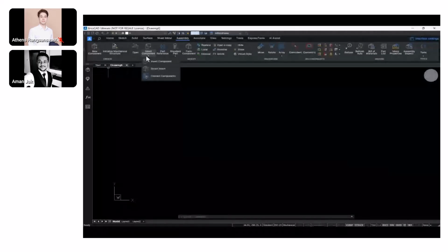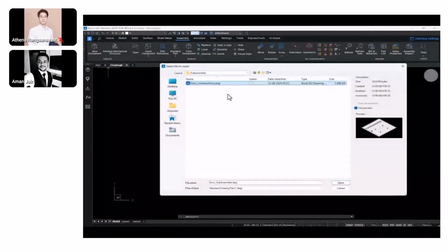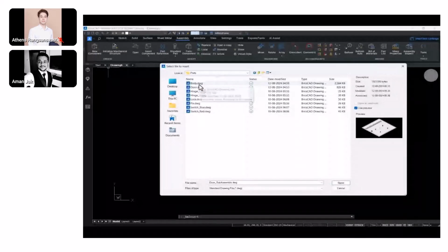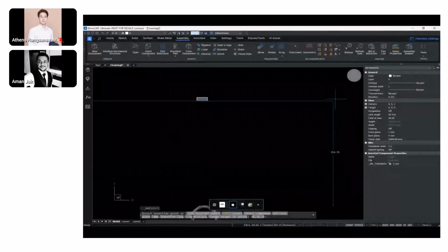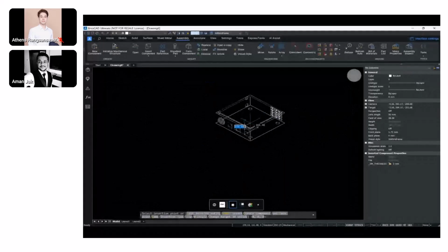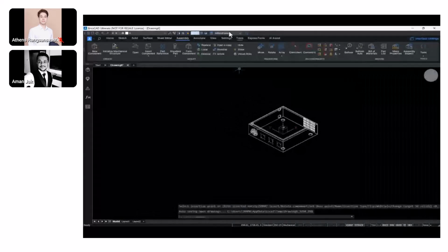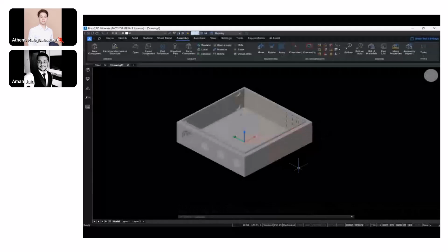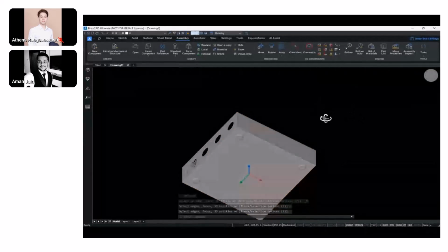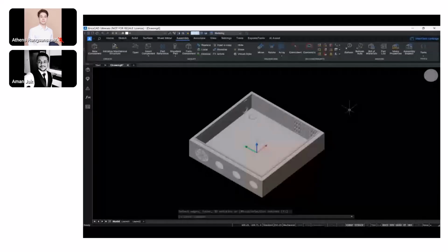We'll insert the component, the body first, because that forms the base for our main assembly. The door would be placed on top of this. So let's place our body and let's fix it so that this does not move and acts as a rigid constraint. We'll make it rigid so that the body does not move as we apply constraints on top of the other parts after inserting the components. Right? So let us constrain this fixed and insert.